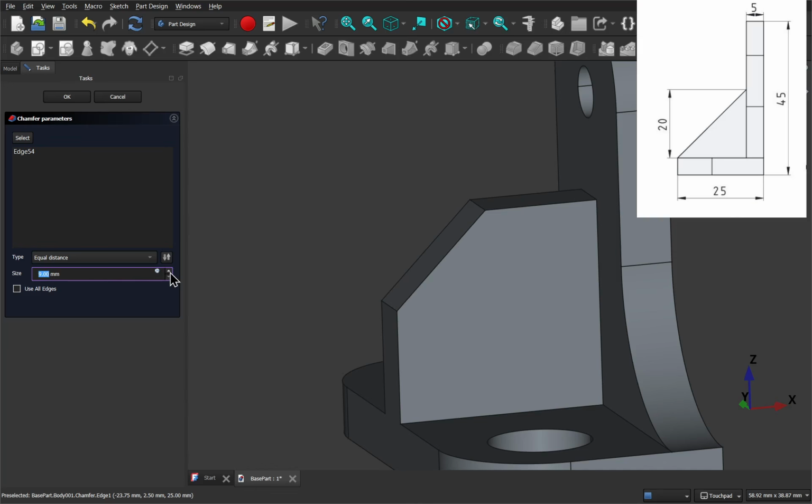This is one of the reasons why I want to demonstrate this feature. As we move the chamfer down towards the base, you'll notice something happens. It's gone back to the square. Look at the size. We have 20 millimeters running down this way. If I set this to 20 millimeters, it still hasn't taken. This will actually cause an error. Let's bring this back to 19.